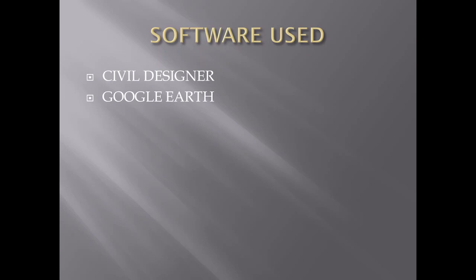So after opening Civil Designer and saving the document, you will open Google Earth, then go to Civil Designer, go into CAD mode, use the tools, then click on External Utilities, select Google Earth, the grid, and from there you will be able to save the picture, the way it is currently set on Google Earth, and it will transfer all the information right over to Civil Designer. Then, as I said, it imports all the information that you need.